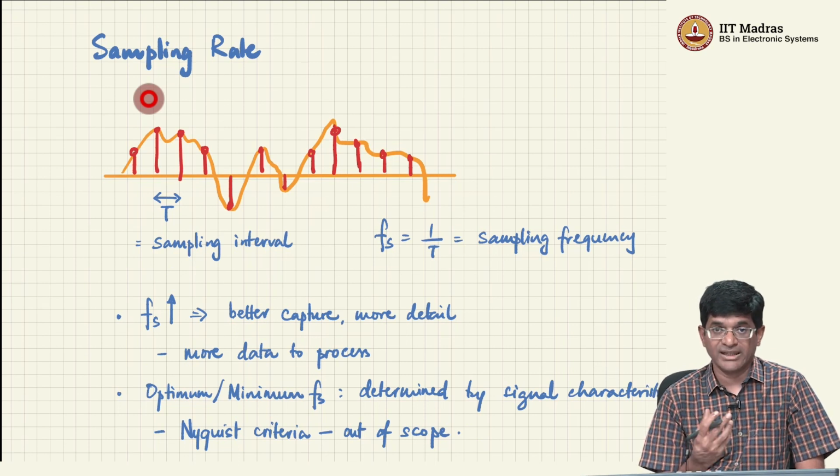Okay, so it's a very interesting result when you think about it, and it can be used in order to determine the rate at which you actually need to sample. The bottom line is, once you go beyond that rate, you are at the point of diminishing returns. You don't really get any real benefits by sampling faster than that. Of course, practical matters are slightly different. You do need to sample a little bit above what is called the Nyquist rate, but going significantly beyond it does not help.